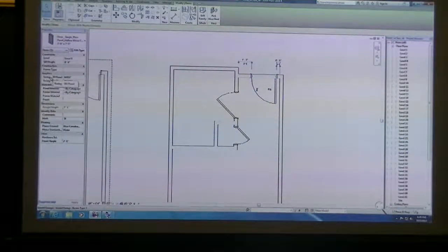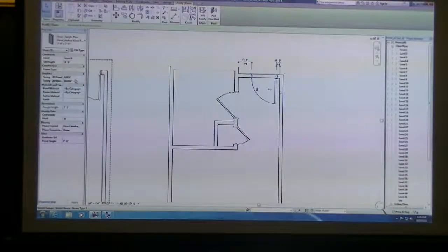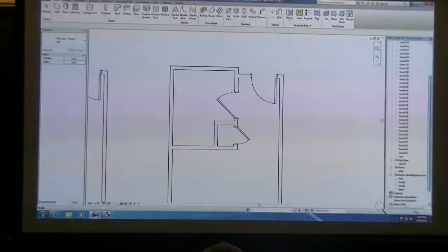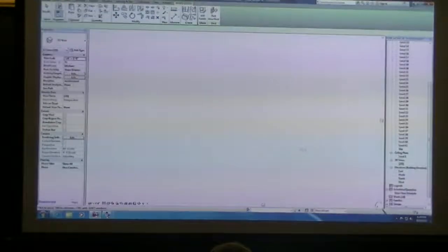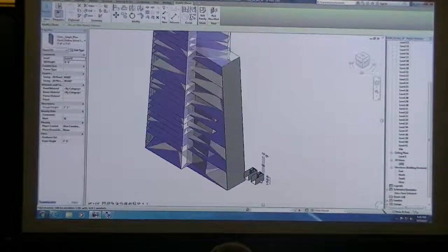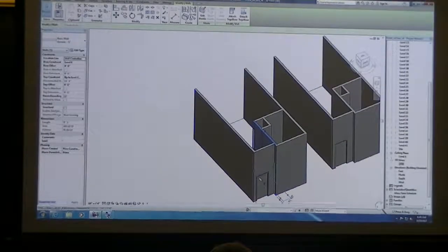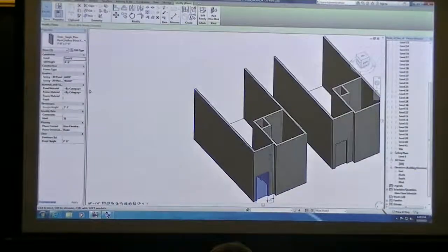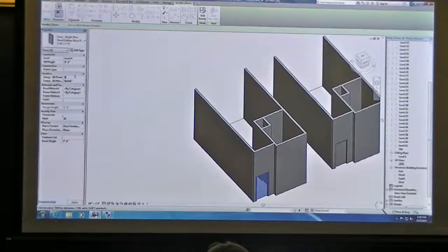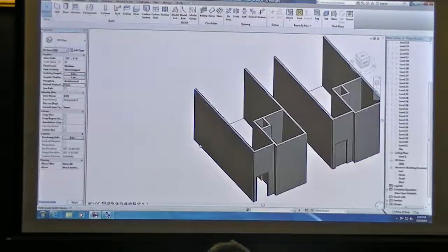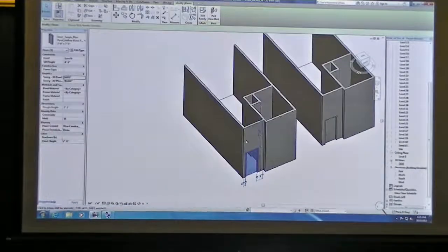And the other one that has to do with the swing in the 3D section, that has to do with if you're ever looking at this in a 3D model. Let's say you were rendering this room and you wanted this door to be open so you could actually see into it. You could use the 3D panel swing, and that door would actually open in 3D. So this door is a little more advanced than what you would typically get with Revit. This is something that we typically use in our office.